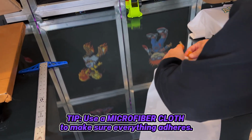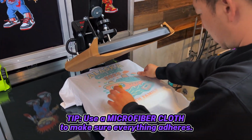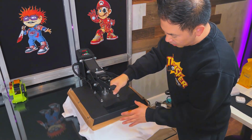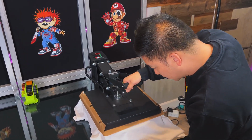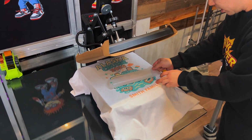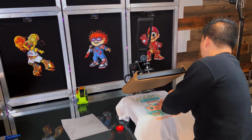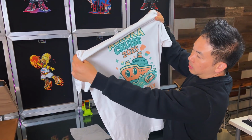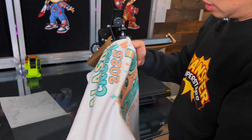And we can either use the back side of this transfer to press it the second time around. What that does is it embeds the DTF ink into the fibers. What you're looking for is the vertical lines that you see on the shirt, but also seeing that vertical line embedded and through the DTF transfer itself. All right, let's take this off. That looks real nice. Nicely embedded in there. I can see the vertical lines on the transfer itself.